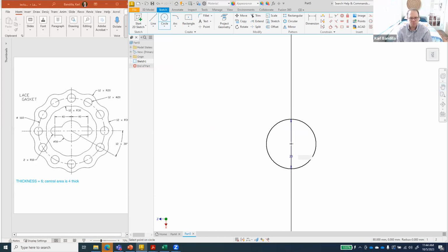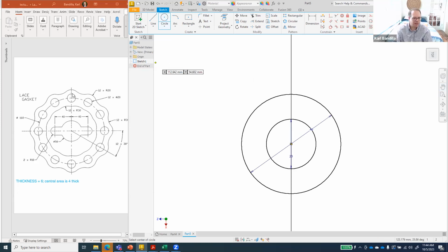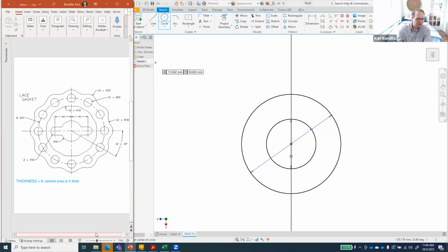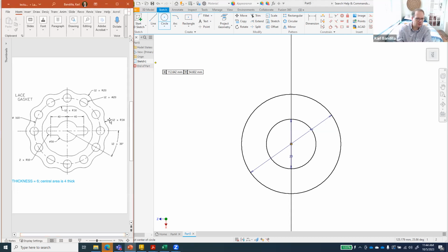So we'll just choose the same place there. We could also have used the concentric circle constraint, but we don't have to add extra constraints. That's better. And so now we have this outside circle. And now the question is, how do we get the other circles, right? We get the information that the diameter of this circle is, for what looks like a 30. Scroll over here, yeah, so that's a radius 30. And on the inside there, radius of 30 as well.